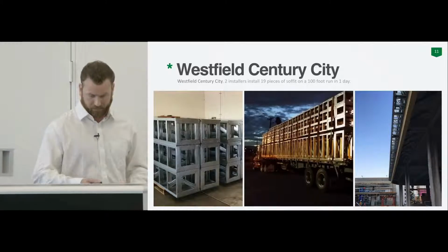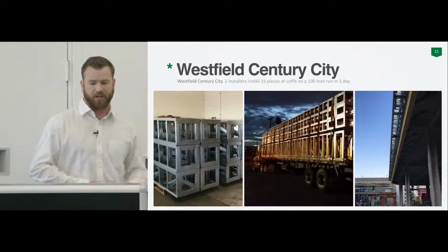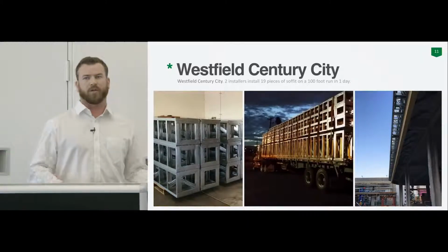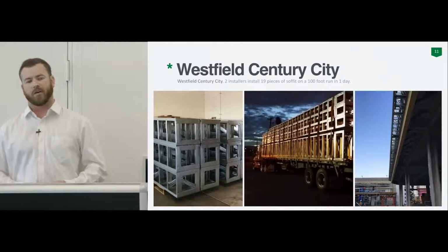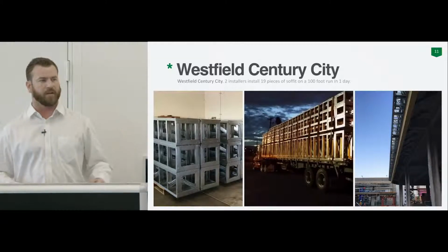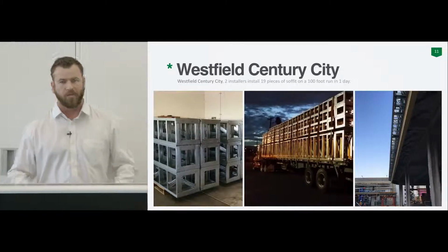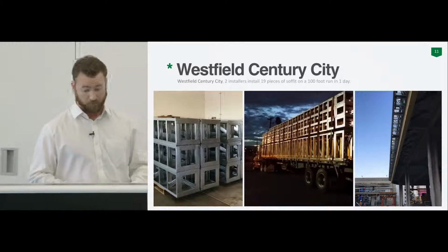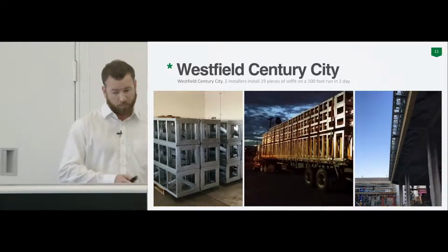So I think it says two installers could install 19 pieces of soffit in a 100-foot run in one day. So we had a crew of 6, put it together, effectively do 800 lineal feet in 2.5 days. So just to put that in perspective, if we were going to stick frame it, same crew would have taken a couple weeks at least. So it's crazy how much quicker and efficient this is, right? So that's a simple project.